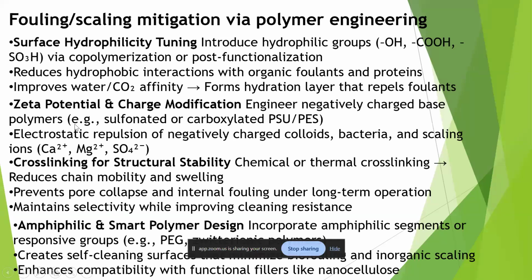Very much related to the work that I did for my CO2/CH4 separation, and the cross-linking in order to reduce the swelling, because the continuous use of a membrane will help in the swelling. So the scaling is an issue. The reduction of hydrophilicity is an issue. The cross-linking is an issue, and certain applications require amphiphilic segments where polymers like PEG, etc., can be used in order to reduce the scaling as well as improve the compatibility and self-cleaning applications.